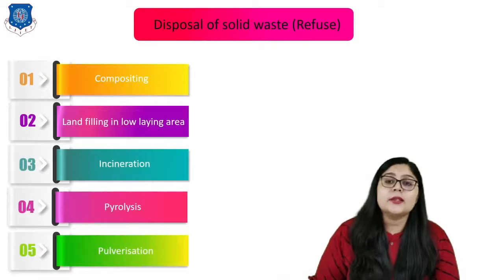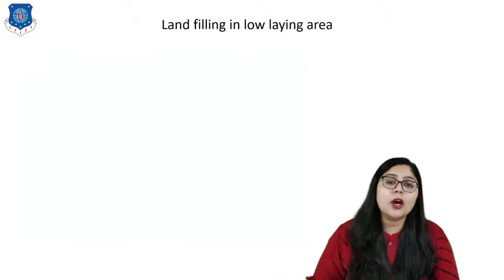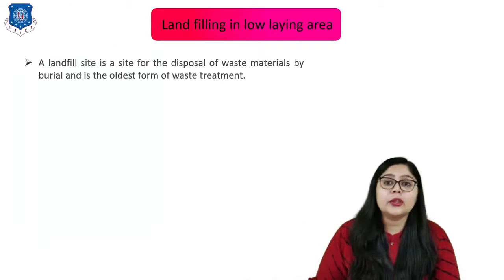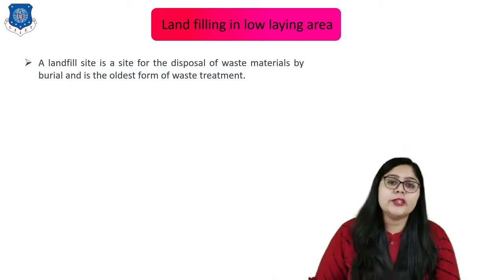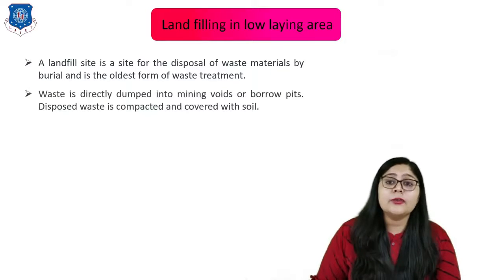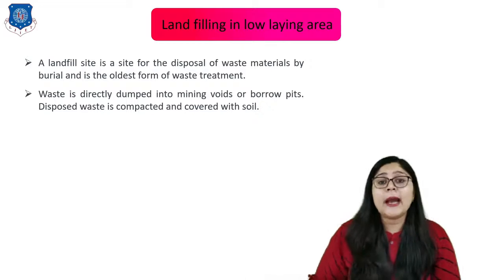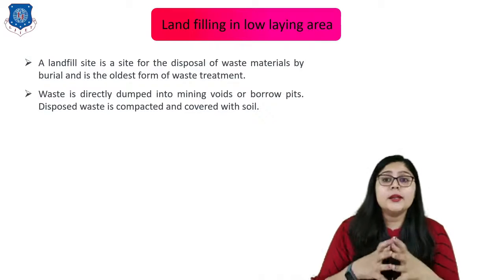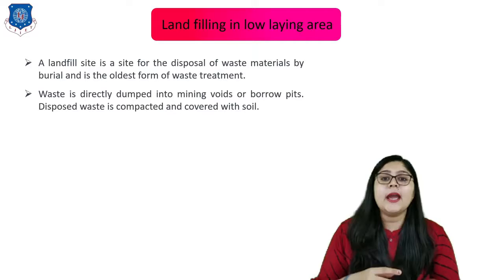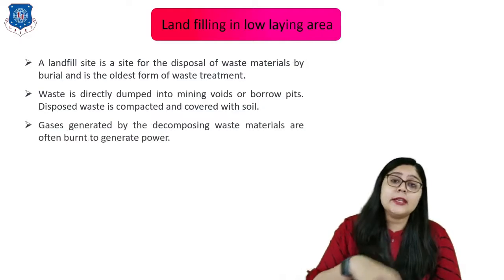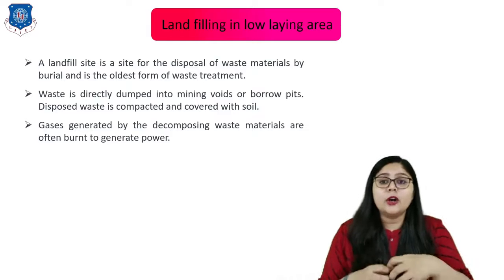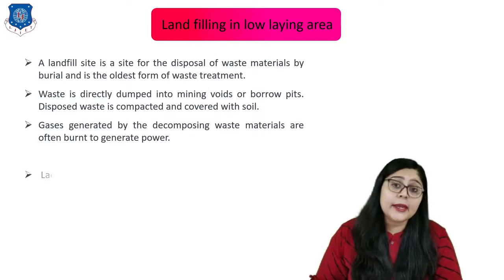Now let us see the second method, which is landfilling on low-lying area. A landfill site is a site for the disposal of waste materials by burial and is the oldest form of waste treatment. Here the waste is directly dumped into mining voids or borrow pits. Disposed waste is compacted and covered with soil. The gases generated by the decomposition of waste material are often burned to generate power.